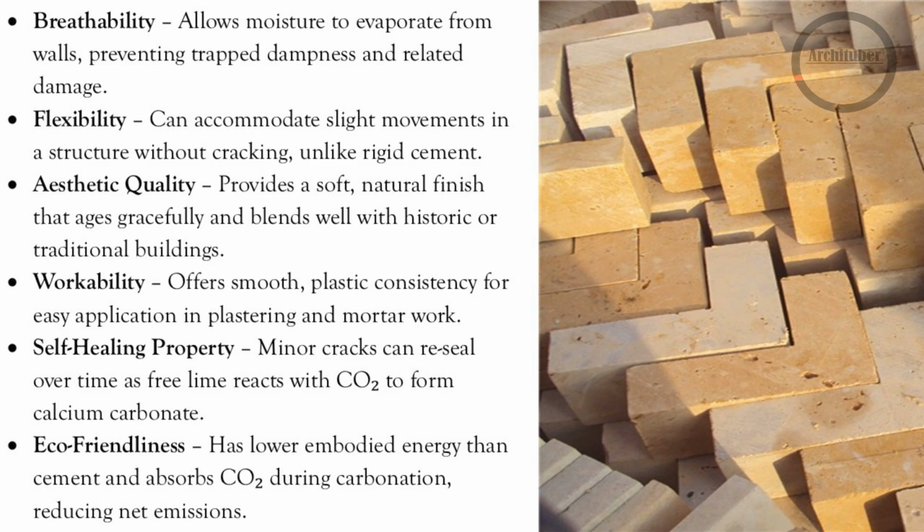Then comes workability. It offers smooth plastic consistency for easy application in plastering and mortar work. Then the self-healing property. Minor cracks can reseal over time as free lime reacts with carbon dioxide to form calcium carbonate. And it is eco-friendly also. It has lower embodied energy than cement and it absorbs carbon dioxide during carbonation and reduces net emission.